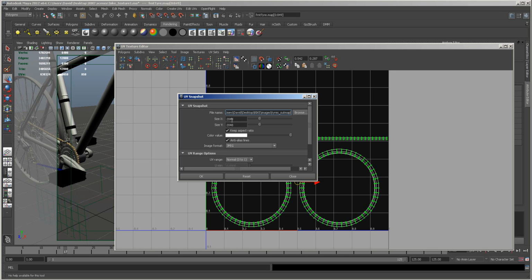You're never going to get that close. In fact, if you're far away, you might even want to drop this right down to even 512. This just gives you the pixel dimensions. Now I'm going to stick with 2048 for my one. Also the UV range I've got in 0 to 1, and that relates to this box here. You could choose other boxes that are other extended ranges, but we keep it 0 to 1 for this tutorial.